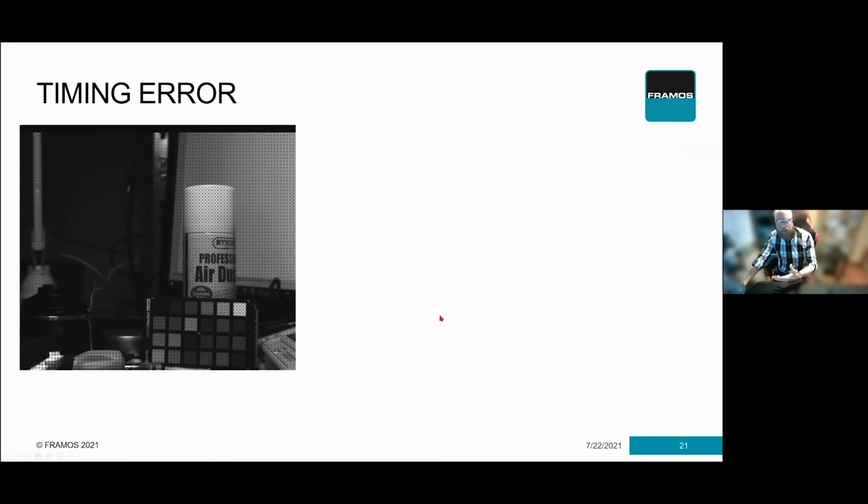One of the main issues that we see when it comes to whether we can see an image is timing. Is it black images? And this is generally based on the internal timing. As I said before, the sensor has both logical and analog sections to it. The analog sections need, let's say, a millisecond to achieve something, whereas the logic side needs a certain number of ticks or clocks. And if you're going to read out something from the analog side and then you change your input clock, for example, you need to therefore change the number of counts it needs to wait for that to be available. The typical one is the ADC.